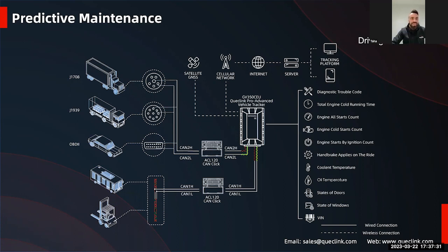At the same time, this port, CAN2, can help you drive more economically and can get you real-time data that you cannot get on CAN1, for example the RPM, the speed based on the wheels, like I said, DTC codes, MIL lights, etc. The same thing for CAN2, it is very easy. For example, with a passenger car, if you want to see the status or health of your car through diagnosis, connect the device to the OBD2. It's very simple.